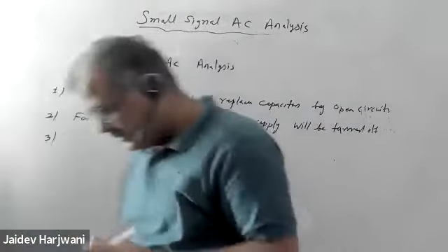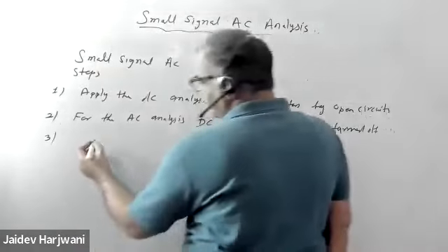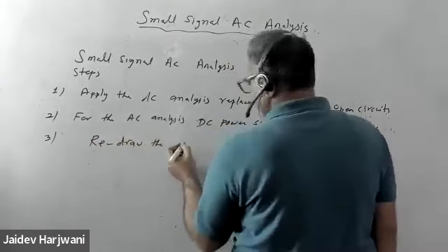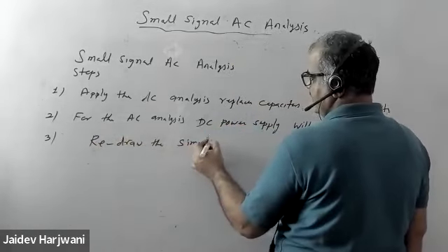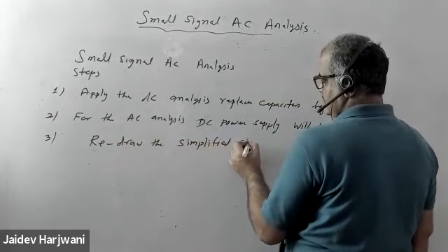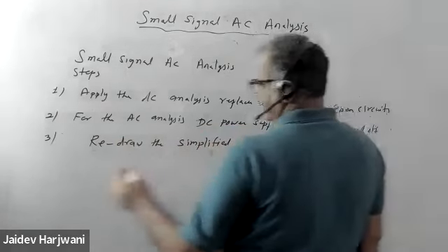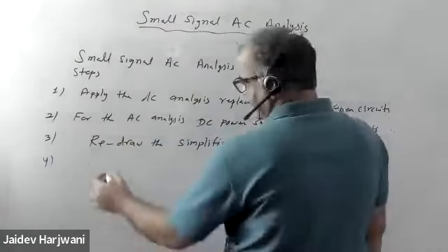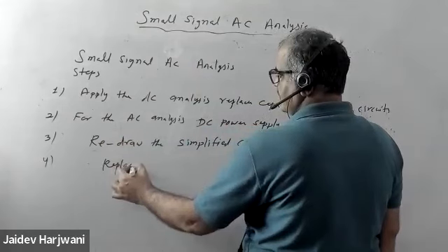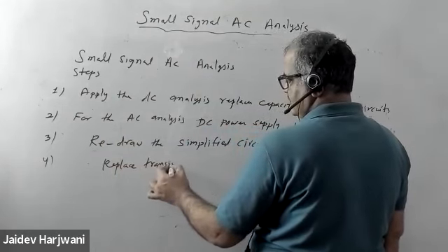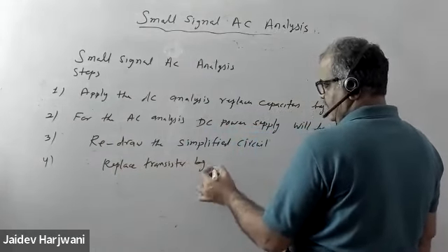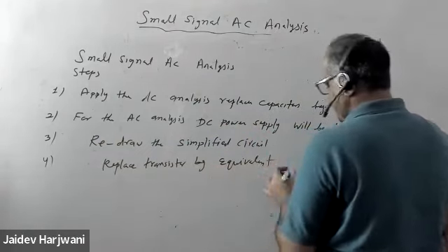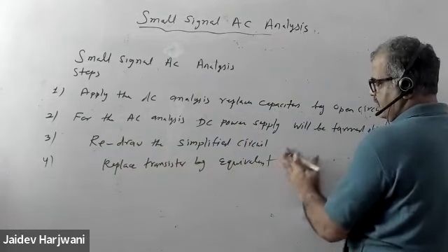Number three, redraw the simplified circuit. Number four, replace the transistor by the equivalent model, the equivalent RE model.